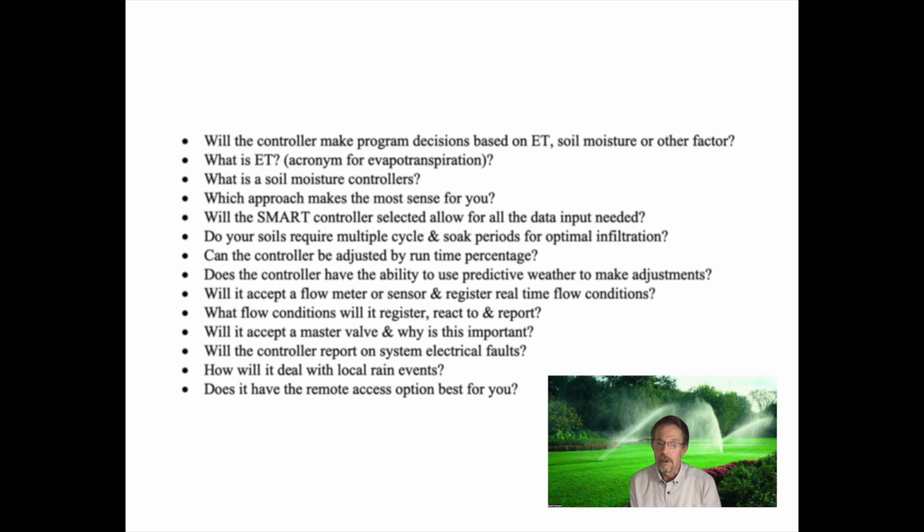Will it accept a flow meter or sensor and register real-time flow conditions? Flow monitoring can tell you when a problem is occurring instead of finding out days later or when you get your water bill. What flow conditions will it register, react to, and report? Events like high flow, high zone flow, low zone flow, mainline breaks, or unscheduled flow, each of which can waste large amounts of water. Will it accept a master valve, and why is this important?